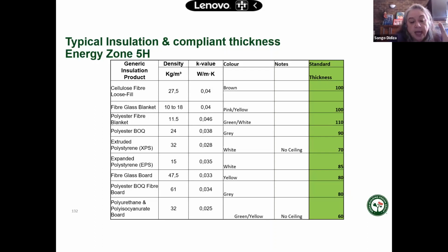Polystyrene is very inert, and that gives its thermal properties, that trapped blowing agent. And that's why the only thing with the boards, the foam products, is that obviously they are combustible. So you have to see where you put them and where you apply them. The polystyrenes, the extruded ones and the expanded ones, are combustible, but they're not toxic when they burn. They've got less toxicity than wood.